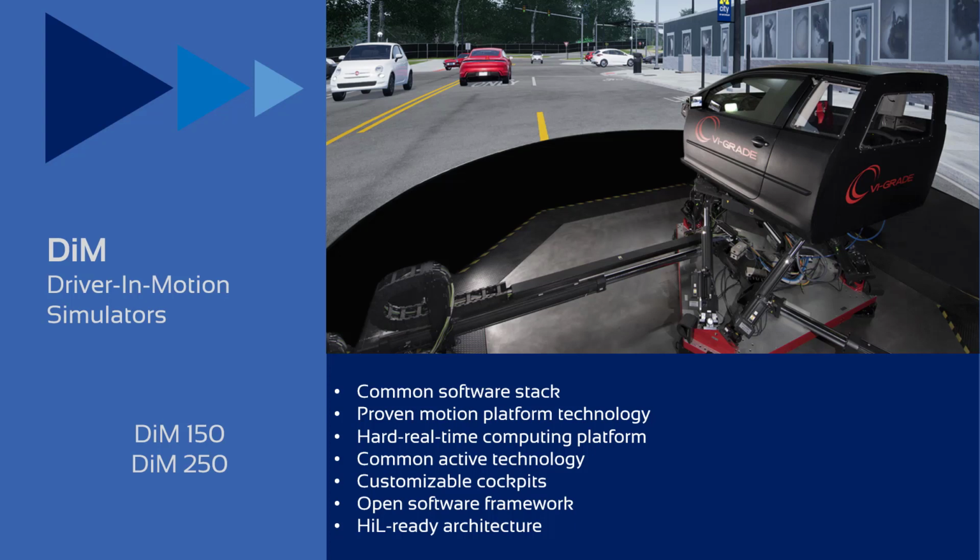These provide 1.5 and 2.5 meters of dynamic travel, respectively, delivered on a 9 degree of freedom air-bearing solution that adds longitudinal, lateral, and yaw response with linear actuators. This, coupled with a world-class motion cueing solution, provides the best vehicle dynamic response.